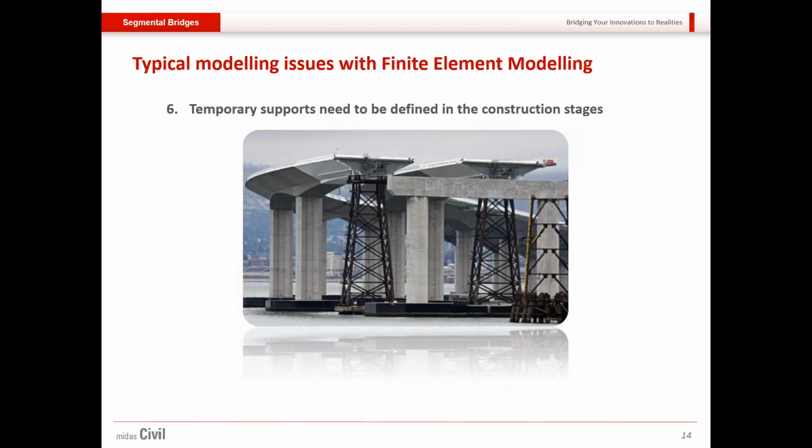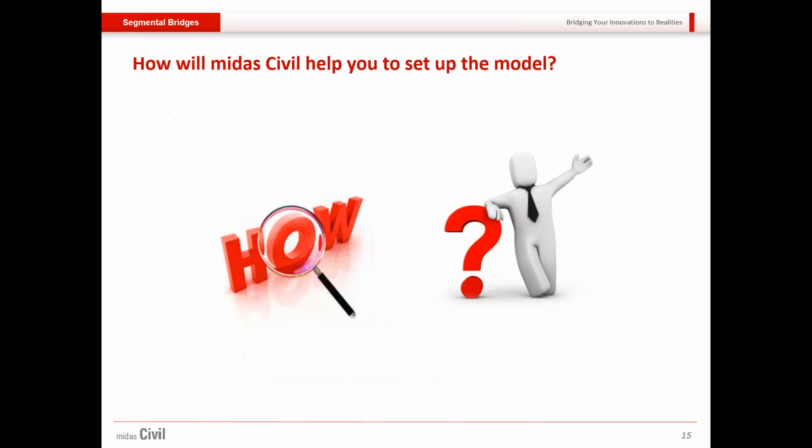And finally, temporary supports might also need to be applied in certain cases. So it could be concluded that the construction sequence, loading sequence, as well as strength of member at each stage play a crucial role in analysis and design of segmental bridges. Failure at any stage is obviously unacceptable, and hence it is mandatory to simulate the construction sequence to verify the same. So these were the difficulties that you would face.